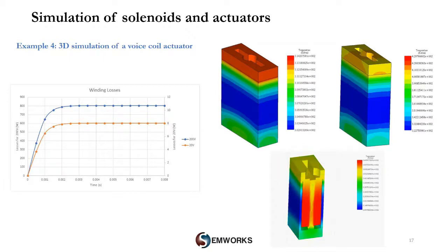A thermal coupling analysis is performed. As we mentioned earlier, in EMS we have the possibility to couple our magnetic or electric simulation to thermal, structural, or motion, or a combination of them. Here we run a thermal coupling analysis to get an idea about the heat generated because of the copper losses. In this case we have only losses coming from the winding, so no core loss, no eddy effects, everything else is turned off, so only winding losses are taken into account.